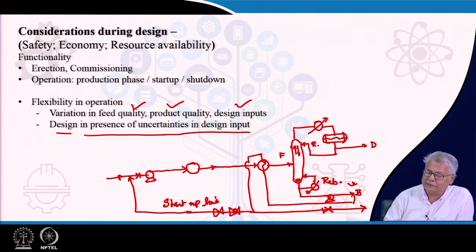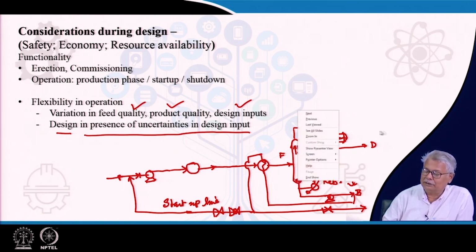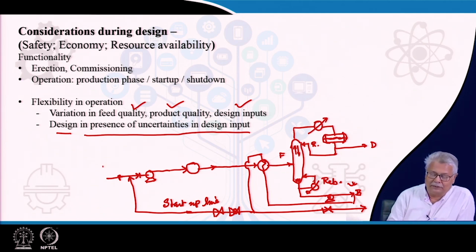After some time the entire column will get heated and liquid will start coming into your reflux drum and your reflux drum will be having a level. Quite naturally, since some of the liquid which had come here while it is circulating, part of it gets transferred to the reflux drum, you have to take fresh amount of feed.